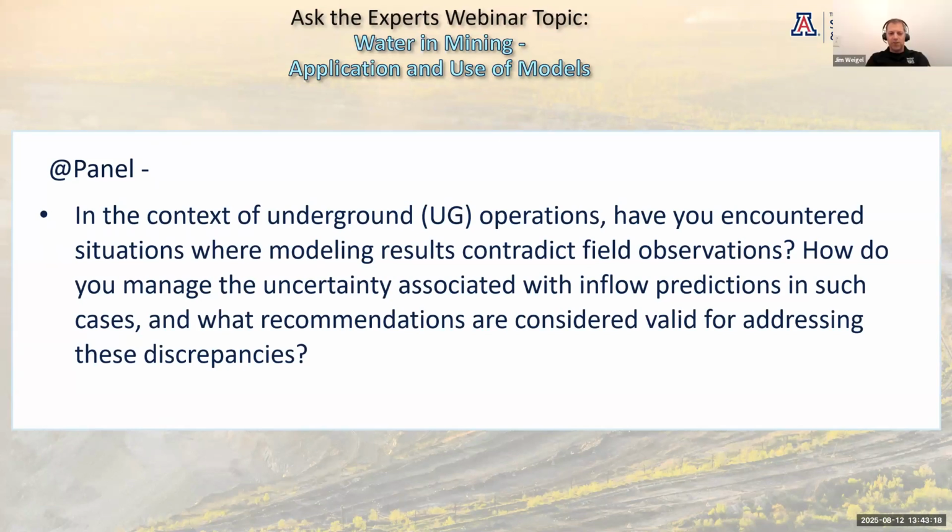Yeah, I think a lot of it just comes down to risk mitigation too, when underground mining is involved and you're using a groundwater model. The models that I've been involved with for underground, we usually intentionally overestimate the inflows just to make sure we have the pumping systems, the capacity, the power, everything in place in the event that we come across those high flow units that Gus was referring to, so that you're able to manage it and not really disrupt operation.